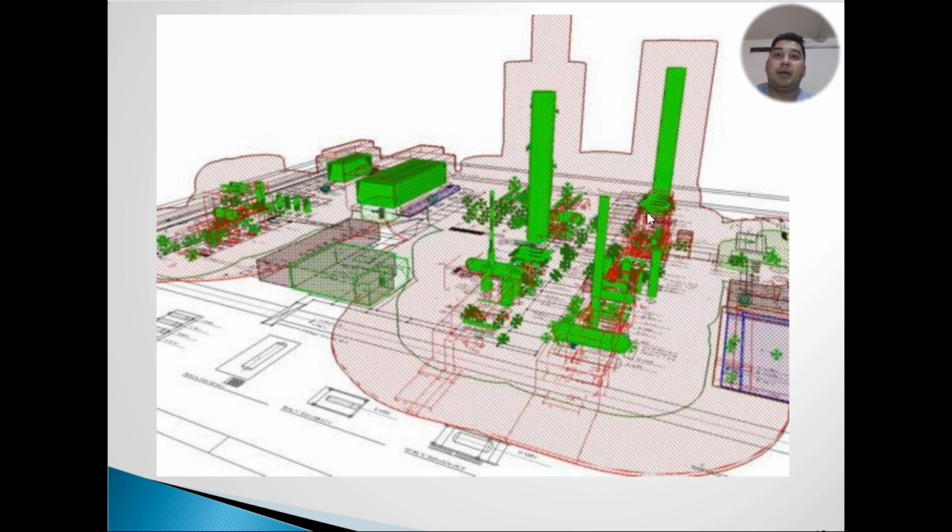So this is the area where we have classified the hazardous area. You can see here there is the green one, then we have the red one, that is the hazardous area classification. So you have to make a location map also, wherever you are keeping any hazardous material. That should be clearly identified, so that normal people can easily identify where you have the hazardous area and how you have classified those areas.